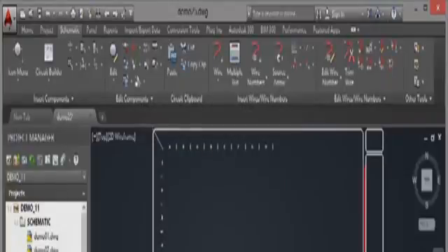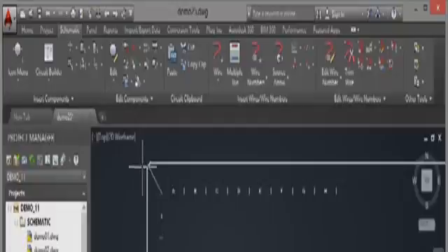Now I've just used the default settings. I haven't actually set up any fonts or any text for this, but if you zoom in, you can see there's the A, B, C, 1, 2, 3, and so on. What I always do is I always try and bring my origin in a bit, hence that little line. That line is actually 2 inches long at 45 degrees. And what I used here was the object snap tracking between that endpoint and that endpoint to get an exact corner, and then just dragged it down.